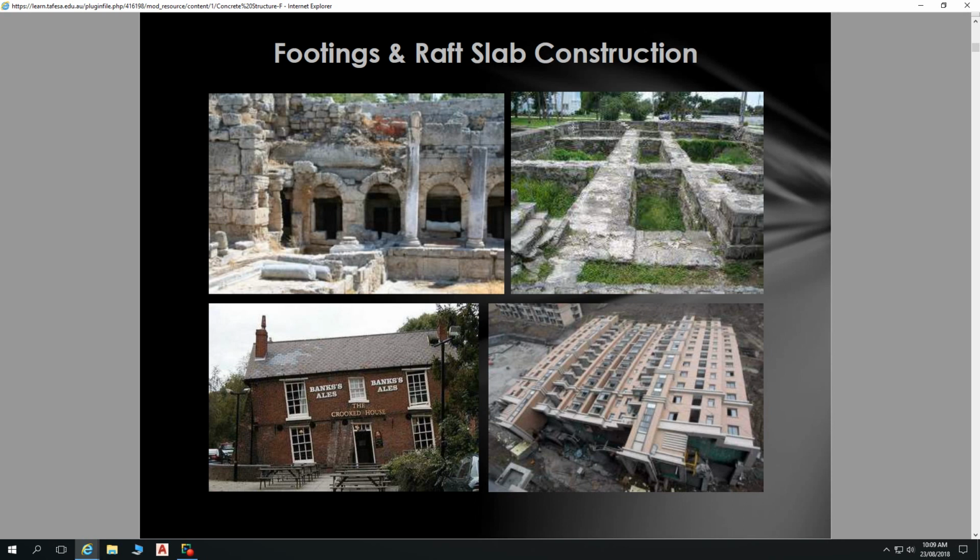So I assume that's just a piece out of a veranda slab. So that doesn't have air in it, that one. Definitely not. See, that one has some steel bars in it as well. However, those steel bars are not the same as these steel bars. That is the remains of this stuff, which is slab mesh. This certainly provides strength in our concrete, but its main intended purpose is to control shrinkage of the concrete, so that we get cracking happening where we want cracking to happen.